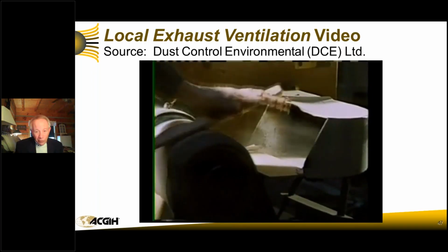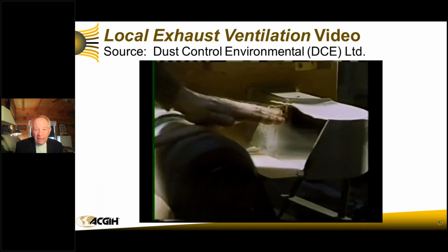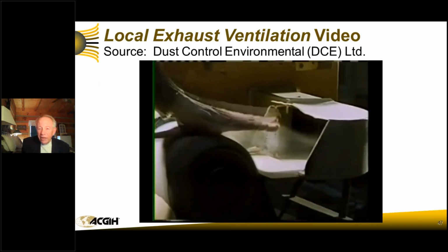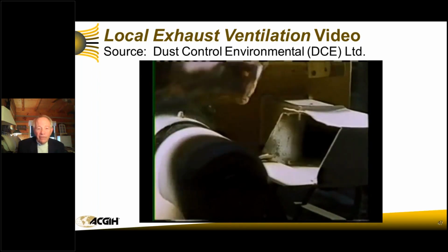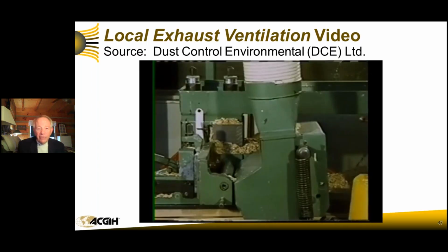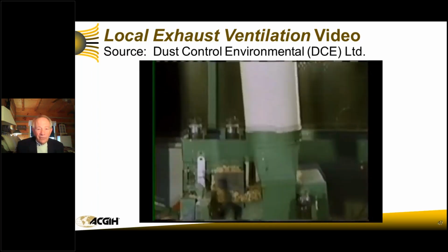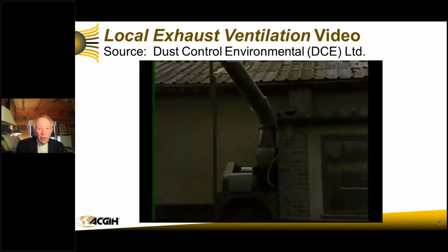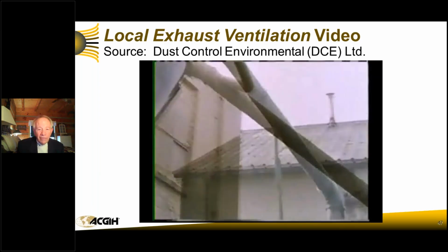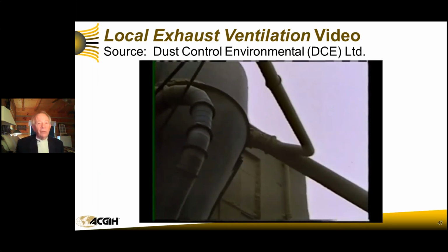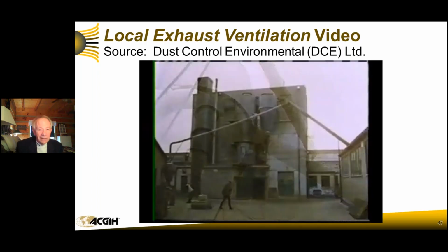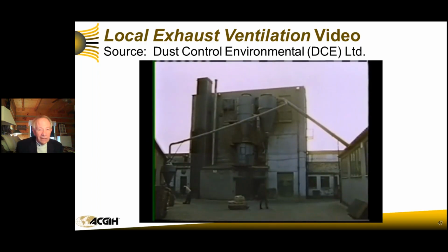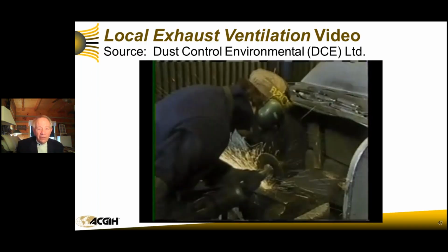Now, local exhaust ventilation, here we go. We're projecting directly in, that's a receiver hood, working very effectively on this pump sander. Here is a planer. We have direct, that's a local exhaust. It goes through a ductwork system all the way out to an induced draft fan that is now pushing through a final contaminant control device, a cyclone. And that goes to atmosphere.